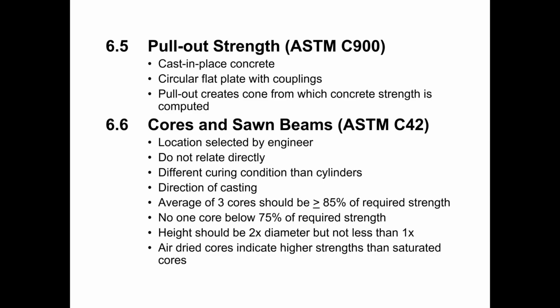I think currently ASTM C42 requires that within a certain period of time of being cut, the cores are supposed to be placed in a sealed container, such as a Ziploc bag, and that they should be stored in that condition until within a certain amount of time of being tested. This way, there's a more consistent level of moisture, and more repeatability in the test results. But one way to get more strength out of a core is to dry it out, and generally it's going to test higher than a wet core would test.